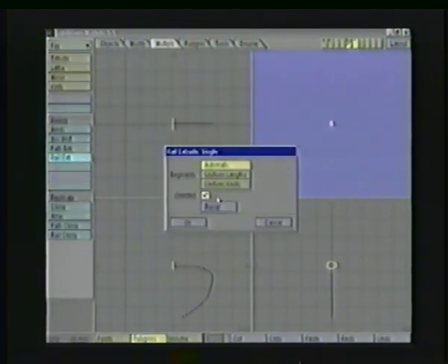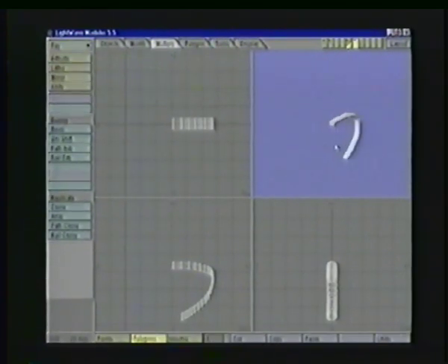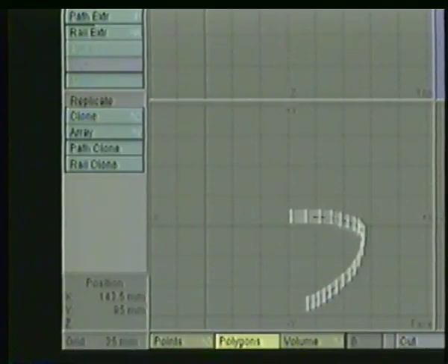Now the last thing we haven't seen what it does yet, or rather we are seeing what it does, is the oriented check mark. If I uncheck that, watch what happens to the extrusion. It flattens out and turns inside out, as a matter of fact. It starts extruding along the curve and then stays vertical and comes back on itself, which turned it inside out.